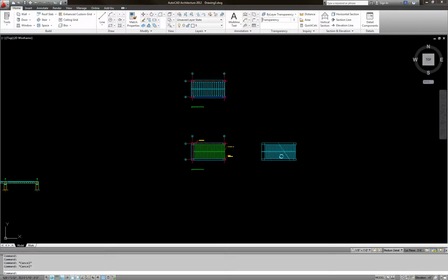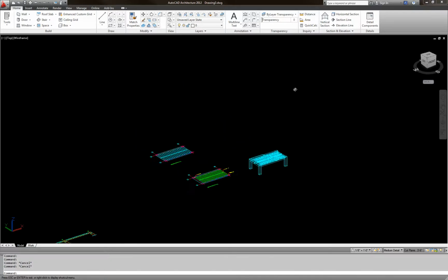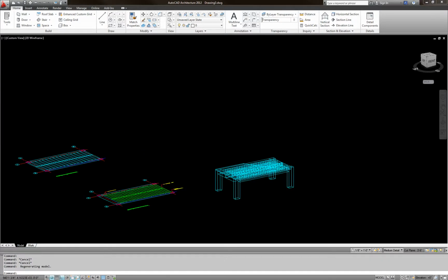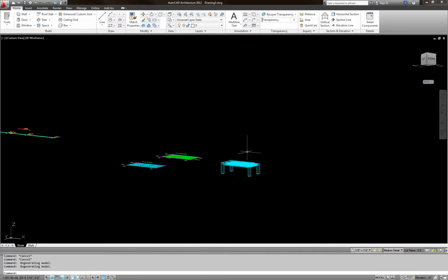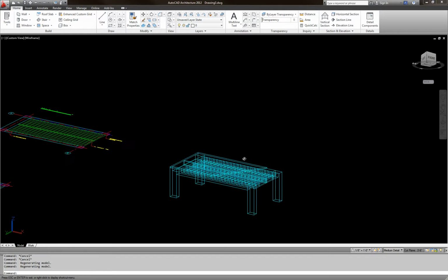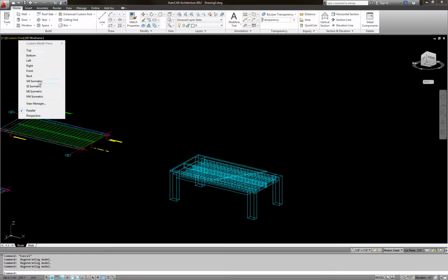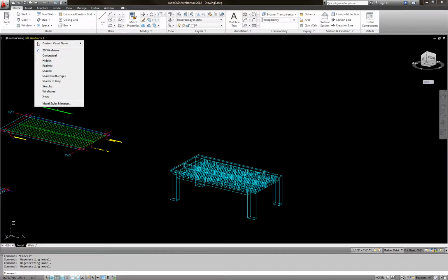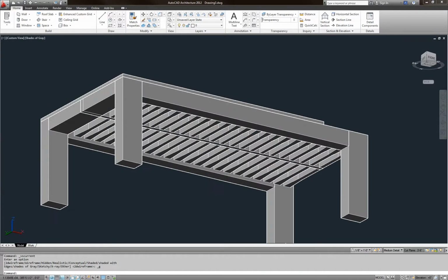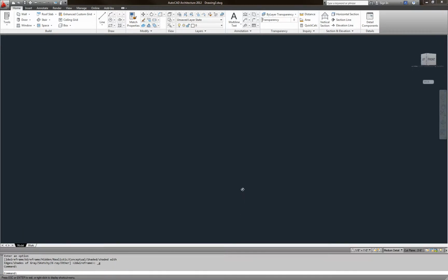So if you look here, if I press shift and press the wheel down, and move around, you could see this. And here guys, this is the custom view. Since I moved my mouse, you could put it in isometric, you could see the isometric. And here when you click on the 2D wireframe, you have different other shaded views.